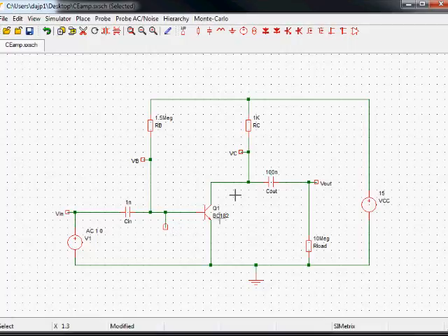And then I could do a similar thing over here, just select that part, duplicate it, move it up here to get the voltage on the collector. Wire that up. Now, that's not going to look terribly good, because when it prints the voltage is going to be up the top here and down the top there. I really want to take that part there and flip it vertically. That's better. Now that's okay for voltages.